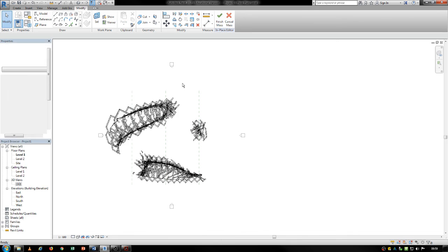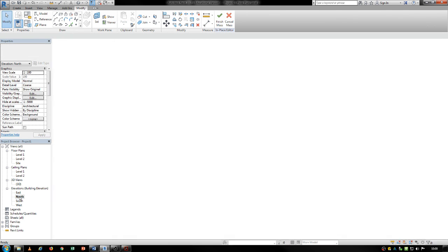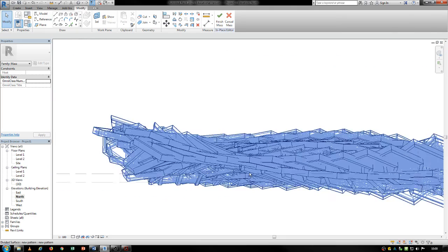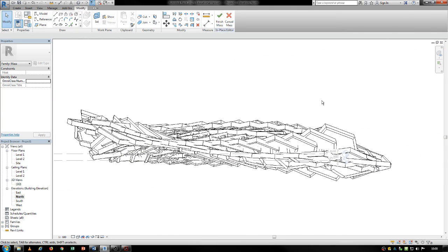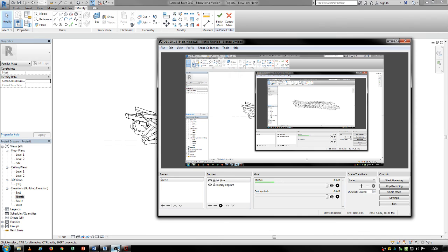The reason it's doing this is not very clear to me, or I would explain that to you. But you should basically be able to apply that grid over this. So instead of defining your surface as a curtain wall, you can just make your components and flow it along the surface to do whatever you want for you. So that was adaptive components.